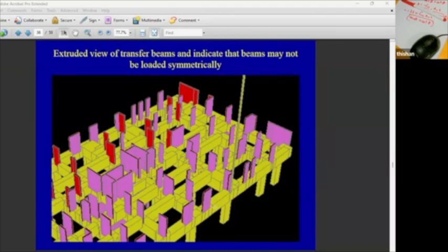But in a site which is large, that may be one of the solutions to avoid torsion, because the moment you get torsion, you will need a lot of reinforcement. The beam can become very expensive. So to reduce the cost, one of the options is to project the transfer beam out and consider it as a kind of visible band when you look at the building from outside.